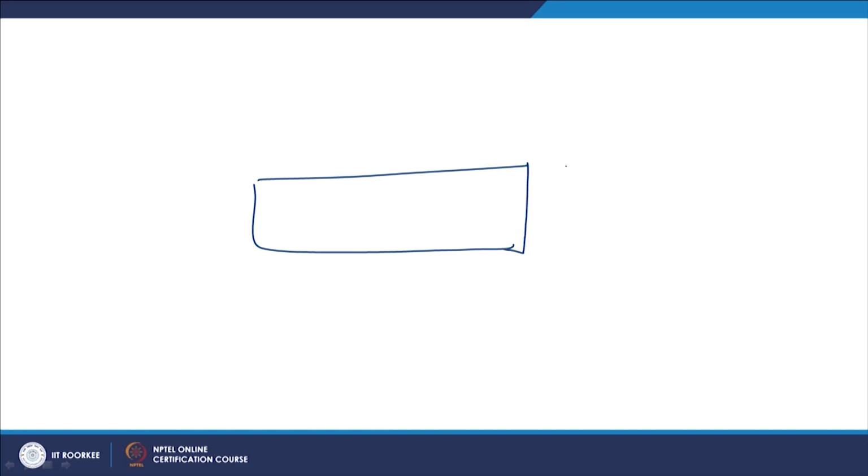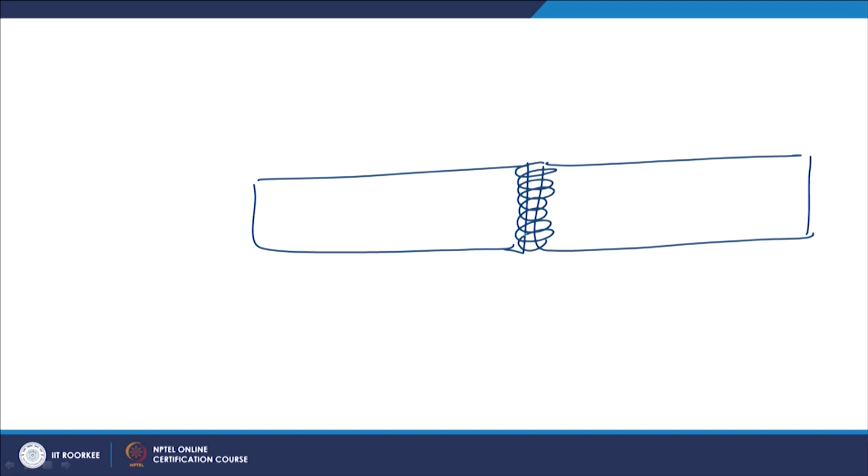Likewise, when the metal system is welded using a solid state joining process, the controlled plastic deformation of the faying surfaces leads to metallurgical continuity. In this process of controlled deformation for development of the joint, some heat will be generated, and that will also generate a heat affected zone. However, the heat affected zone width will be very narrow in this case.